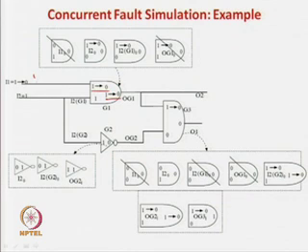Now, this gate corresponded to a stuck-at-0 fault over here. So it was a 0 over here, 1 over here and a 0 over here. This is the old thing that is retained. Now your normal gate will become 0 1 0, because this pattern has changed. So this gate you can delete, this gate we are going to delete. So, this gets deleted.